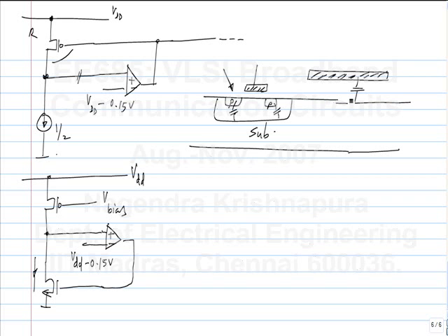So, I may not want to use a PMOS transistor. What do I do in that case? So, I want to keep the swing constant. So, what can I do? I do not want to use a controllable resistor like a PMOS, I want to use a physical resistor, but I want to keep the swing constant. Yeah, actually the second scheme is not dependent on this being an adjustable resistor, right. So, instead of this, I can have a physical resistor, I mean physical meaning a passive resistor, not a transistor, and the swing will get adjusted in exactly the same way. So, you adjust the current so that it has some dependence on the resistance, okay.